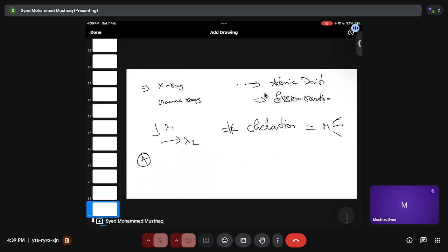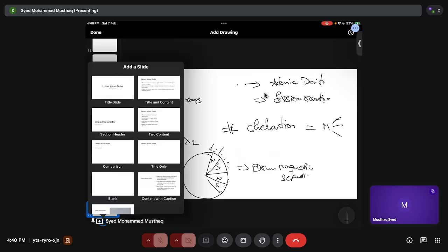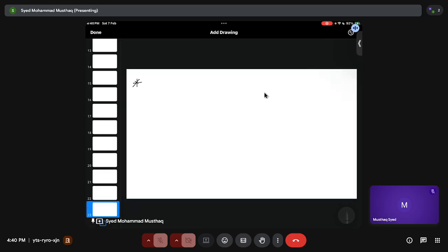Now magnetic drum separators, they have a magnet, north and south, so they have magnetic drums, so the powder particles will get attracted, right? So that's why they call them drum magnetic separators. And then you have the induced magnetic separator, that means you have a drum and then you apply a magnet. Let's say these are north and south, that means you are inducing magnetization in a drum. So that's why you call it an induced magnetic roller.